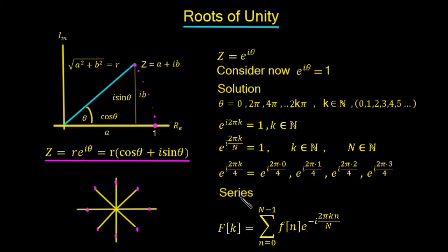So when we create our discrete Fourier transform here, we've got our value of 2 pi, we've got our k, we've got our n, but we also introduce another factor of small n. That small n is our index for adding each of these up, because what we have here is a sequence of these phasors. But really what we want is to go from the sequence of these phasors to a series of the phasors. A series means a summation of them.